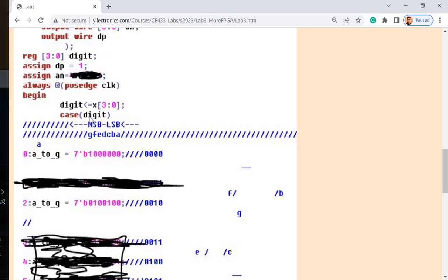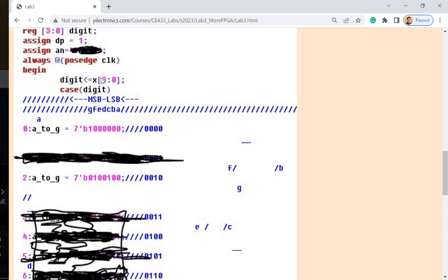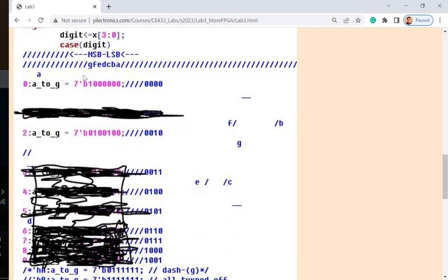But you do need something to update the circuit or the output. If something changes, the clock is going to update everything for you. It's running really fast, so it's okay. And whenever the clock arrives, you update, you check the input of the switch. I'm pretty sure your hands cannot do 100 megahertz to change the switches, so it's okay.